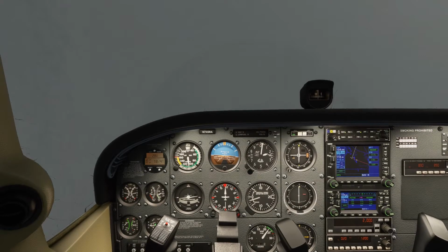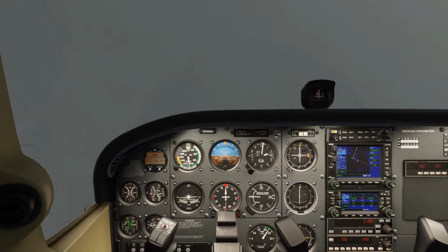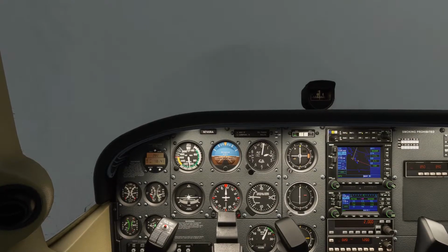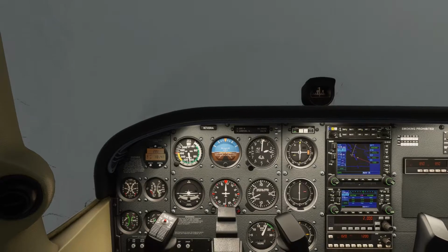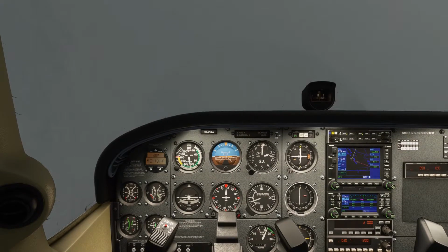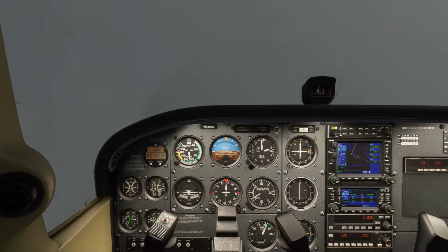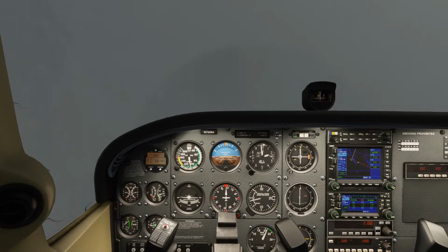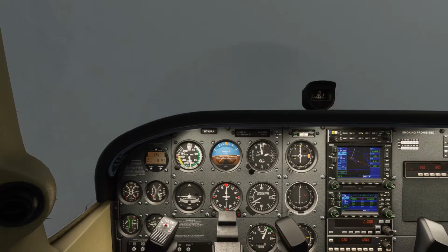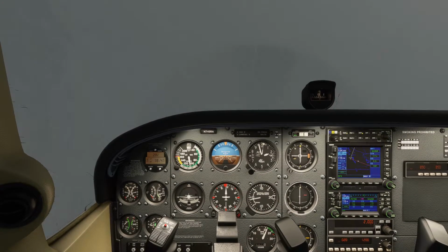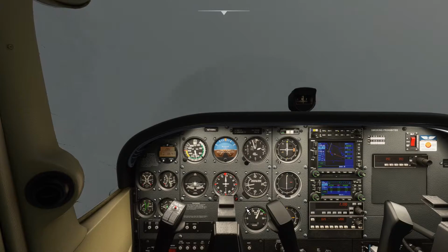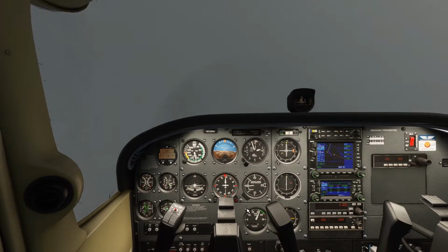Now I can go down to 1600 feet on the way inbound to Maina, so I'm just going to reduce the power by a couple of hundred RPM, let the nose come down. No need to retrim the aircraft, as we're not changing the airspeed, and then I can just allow the aircraft to gradually come down to the 1600 feet platform altitude for Maina.